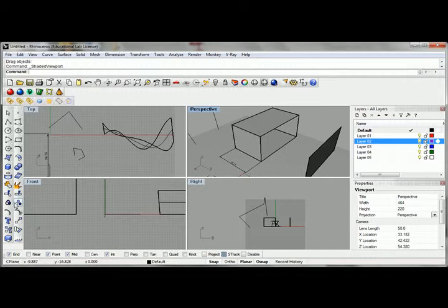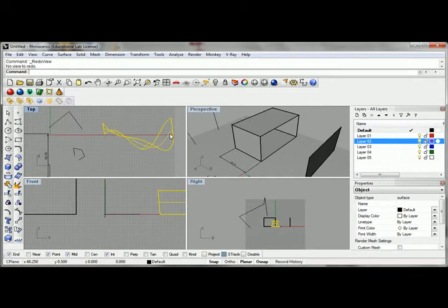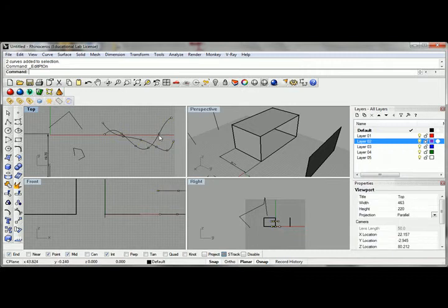We can group. Generally speaking, this is not the best practice because it starts to make you feel like things are joined when they're actually not. So that has implications, again, when you start to generate closed geometries or try to control surface orientation, things like that. We can start to reveal information about curves. I'm just going to go ahead and delete the surface away here. We can turn the control points on, and we can change that as well. There's two different views. We can go to the weighted controls or the actual points on the line.